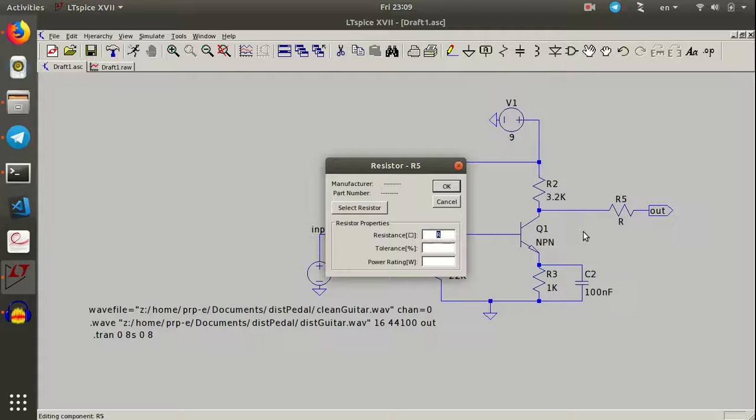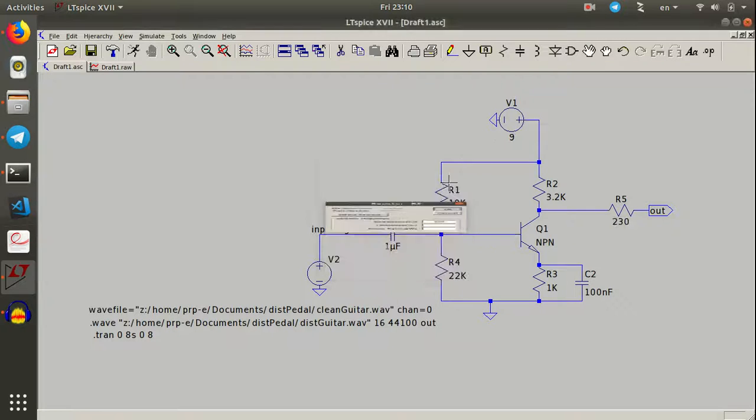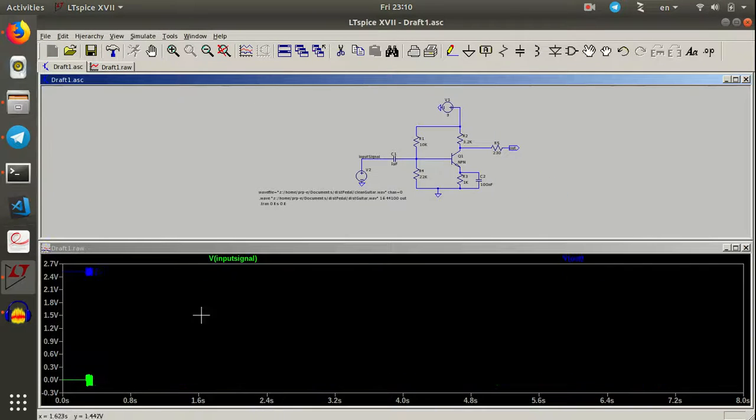So this is the duty of the mixer, audio interface, or sound card you connect to your computer to keep that voltage level safe. If I add 1 kilo ohms of resistance, it kills lots of power there. So I add 230 ohms of resistance. Okay? So let's test it again.